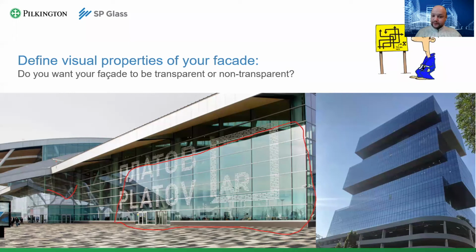Mind you, this is a very transparent glass. This is Suncool 7035, so 70% light transmission. On the right, your facade has much darker glass. Here light transmission is 40%, yet you can look through. Why? Because the sun is behind the building, and the level of light inside the office and at the viewpoint of you, the viewer, is more or less the same. So here, with the much darker glass, you see through the facade, while here, you have some difficulties in this part.